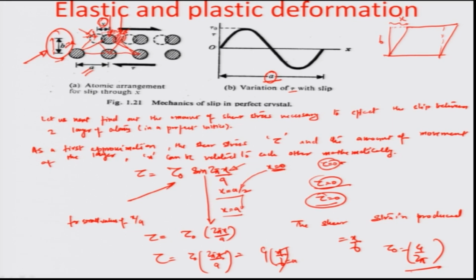So, that is going to be the amount of stress required in order to execute any kind of motion. It is actually the ultimate shear yield stress value which would be needed for creating the motion in question between the atomic planes. You can see that tau 0 corresponds to the maximum value when x is equal to, let us say, a by 4 or even 3a by 4.